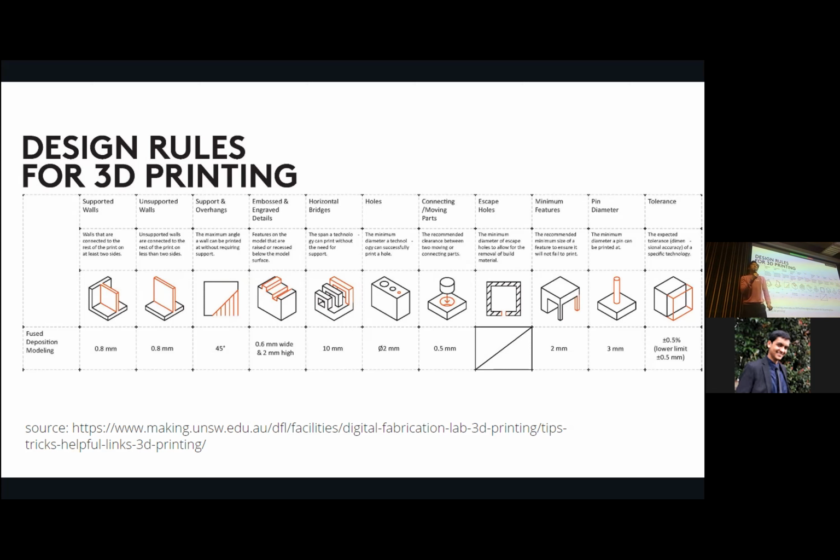Usually, if you're printing an overhang, it's hard to get away with it. But if you're making a bridge, right, you can actually get away with quite long bridges. Last night, I actually did manage to get a 140 millimeter bridge, which is quite long, and usually you wouldn't do that. But if you have a good printer, you can get away with it. Big flex.